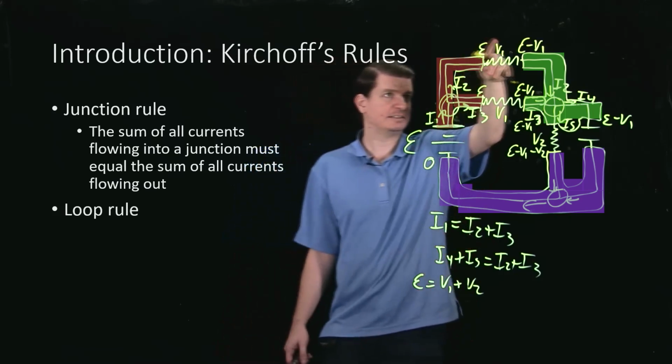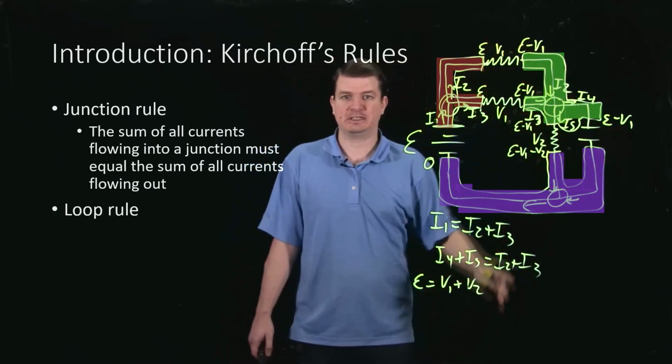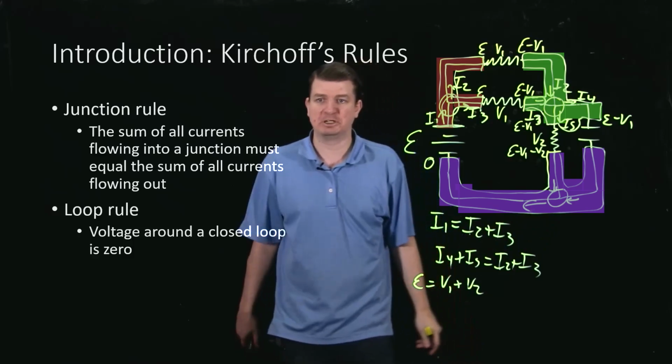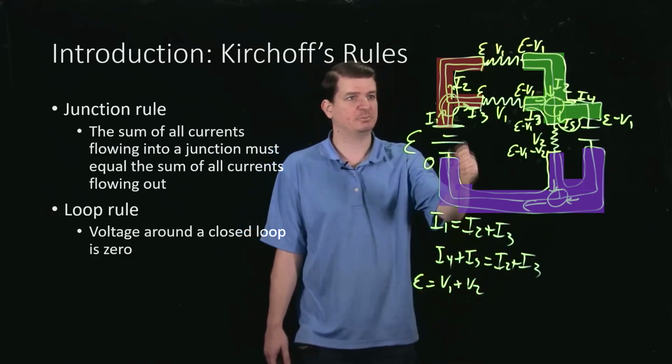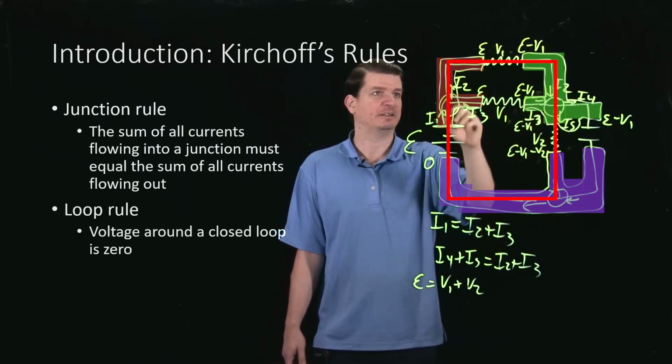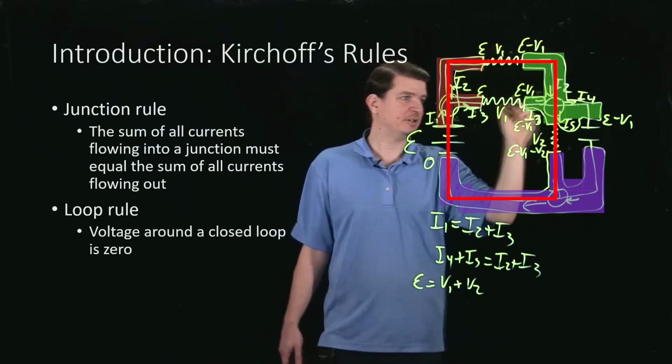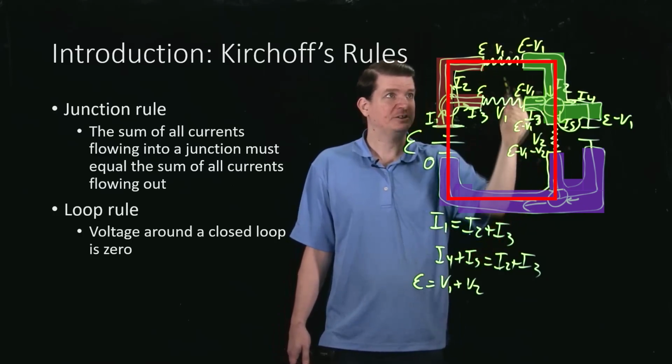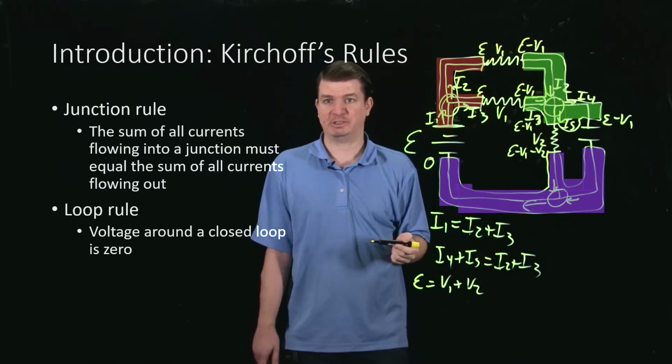So we can shortcut tracking it like this through everything and talking about equipotentials. And just remember that the voltage across any closed loop, so I was just looking at this loop originally, has to be 0. I know that this loop, same thing, so that EMF and that EMF have to be 0. Which is again another way of proving that it has to be V1.